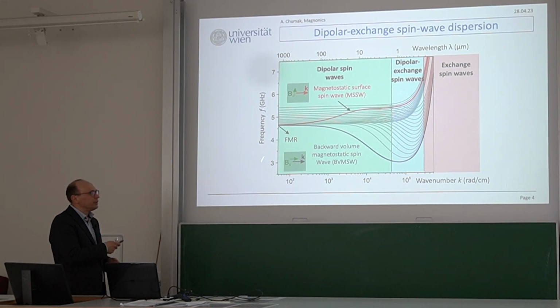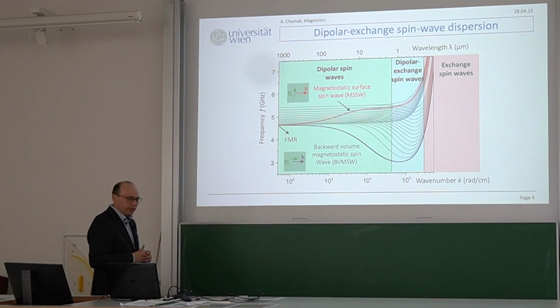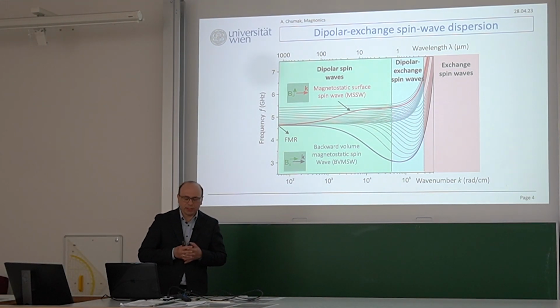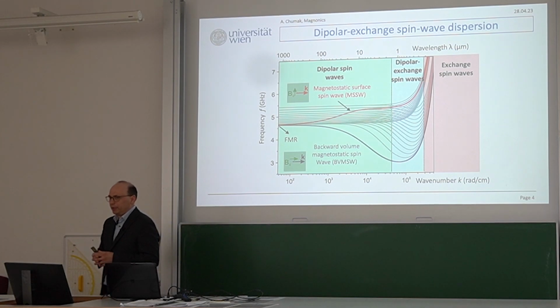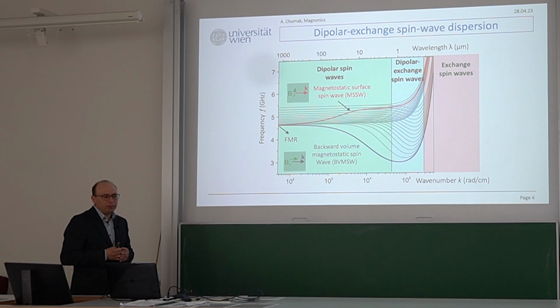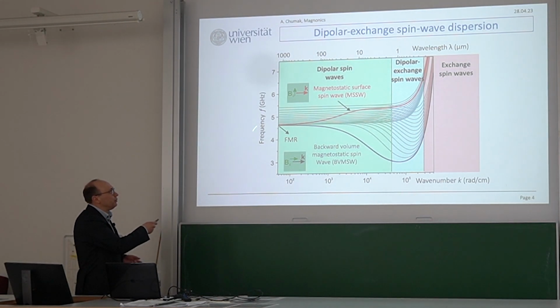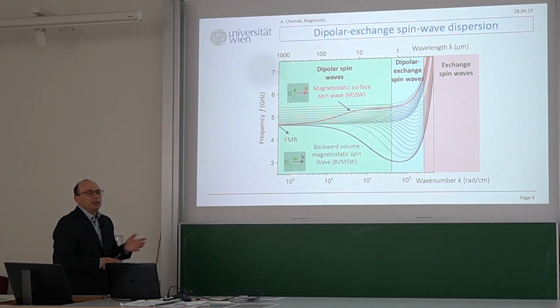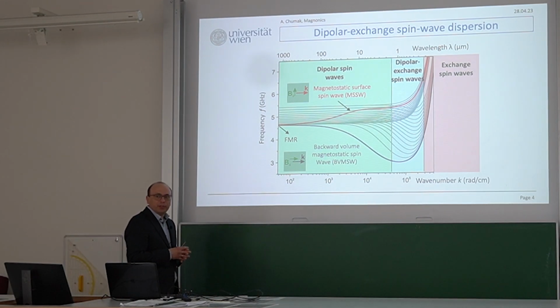And this is very good because the 3-magnon splitting has a very small threshold, so even at minus 20 dBm or so, you already see damping, a parasitic effect. And it pretty often creates problems for your measurements. Therefore, what people do is just increase the field a bit, and then 3-magnon splitting is forbidden, and so on.